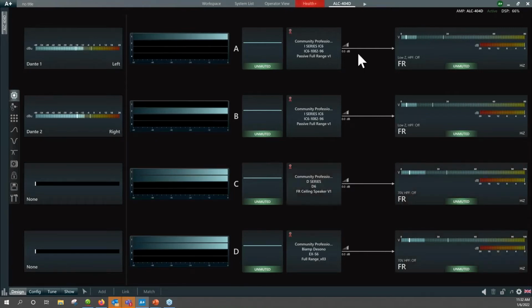Now, another thing to mention too, there are attenuation controls on the front panel of the amplifier. So the left side front panel that comes off behind the mesh, there are blue knobs. If you were to attenuate those blue knobs, you'll get a reading here of what your attenuation is. So on site during commissioning, install, if you just need to make quick adjustments, you can turn those knobs. I highly recommend leaving them turned full clockwise.